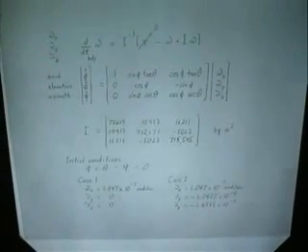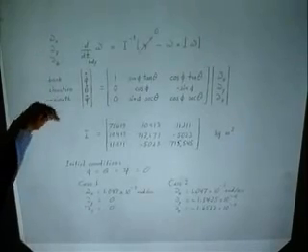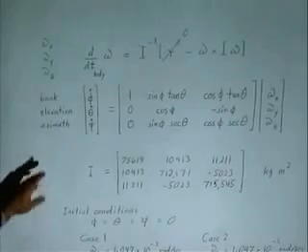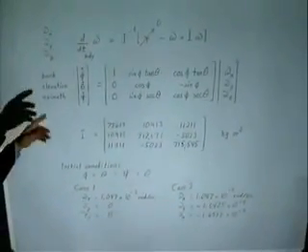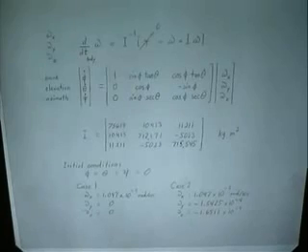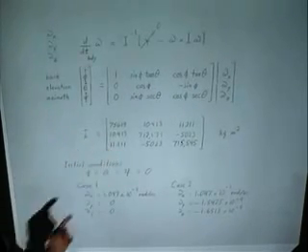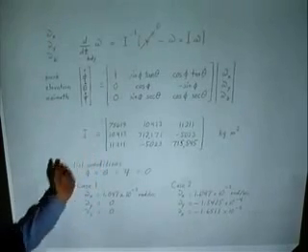You have to integrate 3 Euler angle equations to keep track of the attitude of the spacecraft, and you have to integrate 3 angular velocity equations to keep track of the angular velocity. So you have 6 first-order differential equations that have to be integrated to see what the motion's going to be. And this is the inertia tensor in body axes, not principal axes.